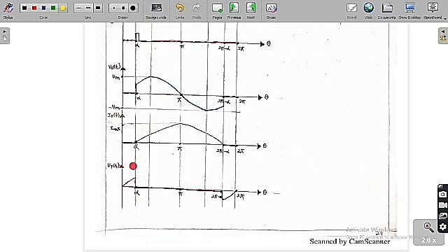So now you will analyze the voltage across the thyristor in this case. I have already told you, from 0 to alpha the thyristor is in forward blocking mode. So it is going to act like an open circuit, and the output voltage is equal to 0. So the source voltage should be equal to the thyristor voltage. So it is going to follow the source voltage.